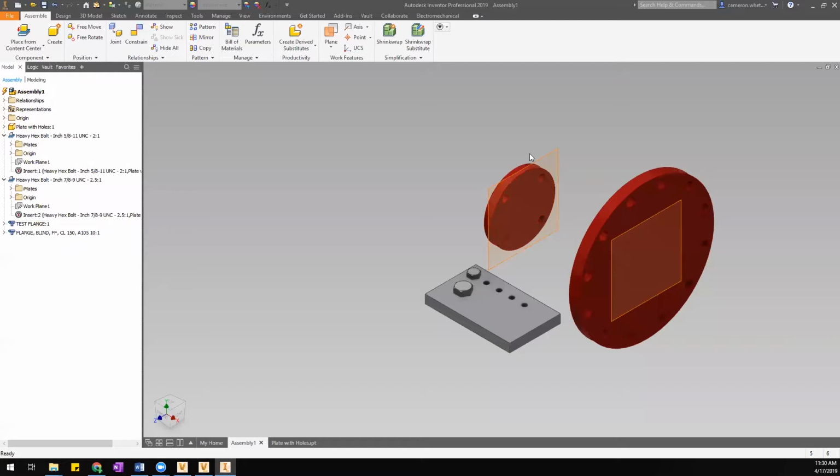It's because I knew that when I was going to place a custom part, it needed to be from that family. So the family had to exist first. If I had made my changes to one from the raised face family and then gone in and copied the family to make the new family and tried to replace it from the other one, it just wouldn't work. So that's probably the most important thing to remember there.